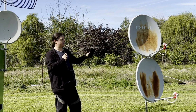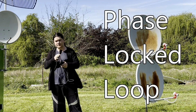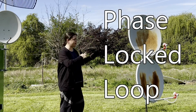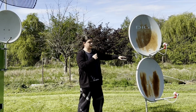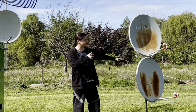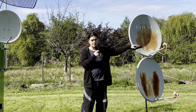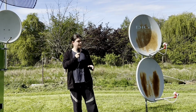You have to make sure that the LNB you are getting is a PLL LNB. PLL refers to the type of technology used to actually generate its local oscillator frequency. Again, as usual, 75 ohm coaxial cable used with a 50 ohm SDR doesn't matter. You don't have to worry about that, especially not in this case where the conversion gain of the LNB is absolutely insane. And that actually is a good thing I'm mentioning that.